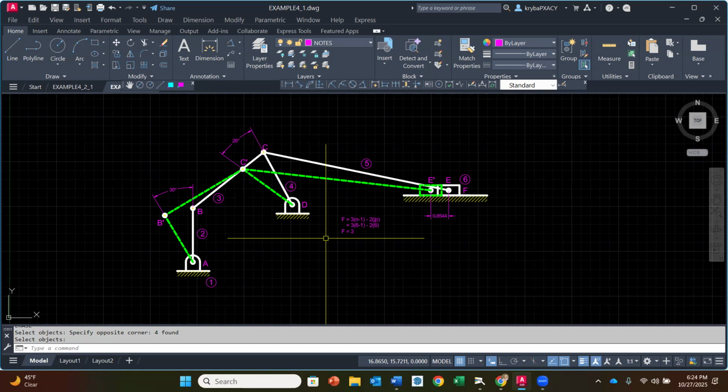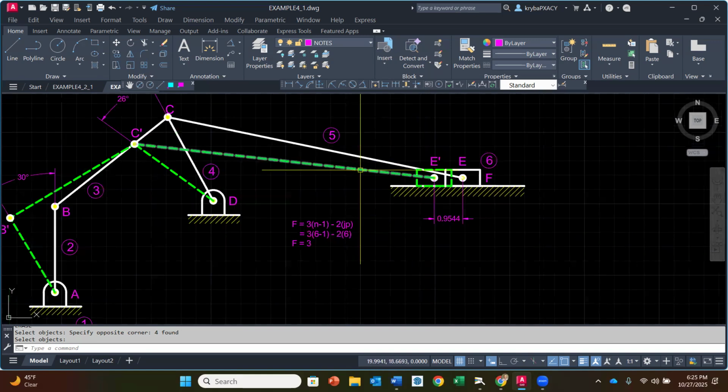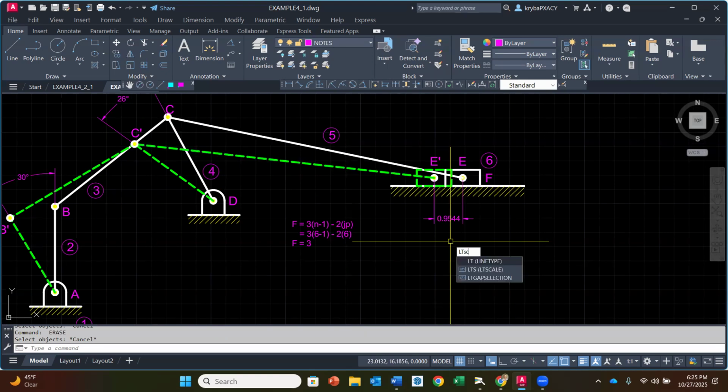Yes, Nicholas. So, with the green lines, for some reason it's not letting me see the hatching, and I missed the part where we added that dash line to it. I have it selected as dash line, but all of them are solid looking. Okay, so then remember from tech drafting, you can put in the command LTSCALE. LTSCALE means line type scale.